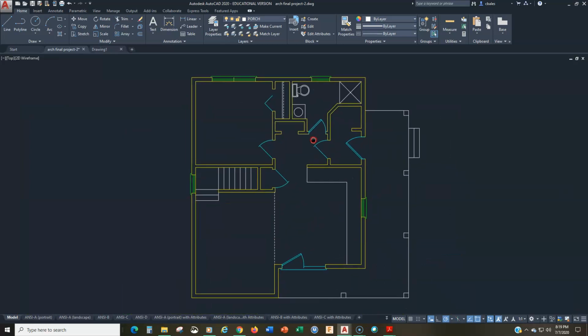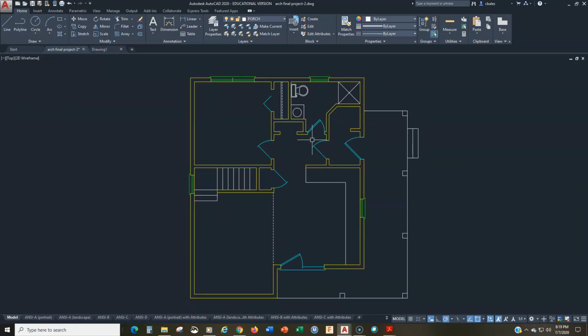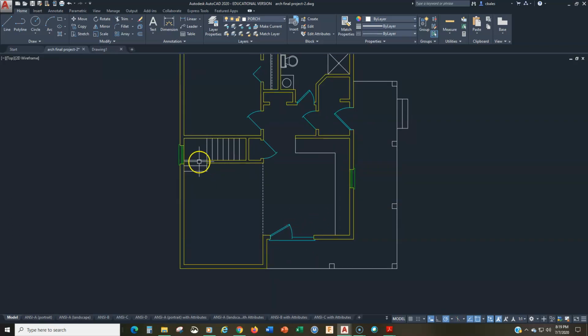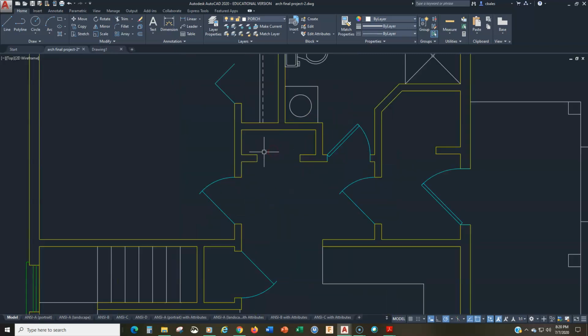So there is some artistic license that you're allowed in terms of how you draw appliances and doors and things like that. You just make it look good. Use your best judgment on this. Where things are not explicitly dimensioned, you have the license and ability to get in there and make it look the way you would like it to look. Just make sure that you follow the principle of line weights. Right? Color doesn't matter. Line weight is what's important.